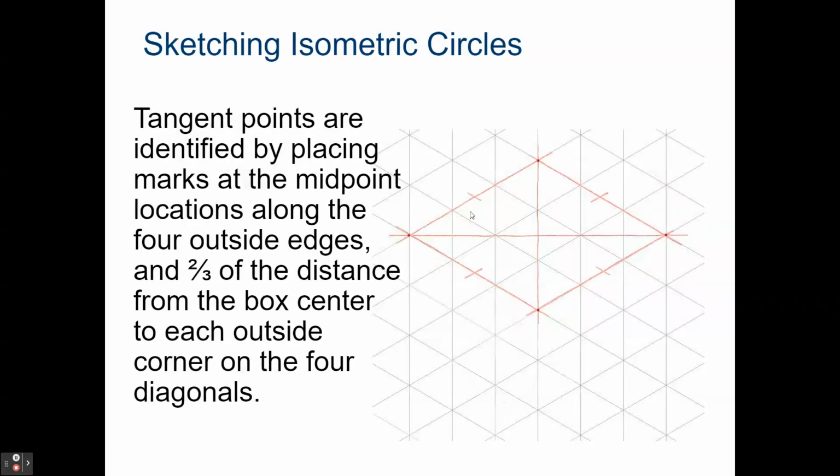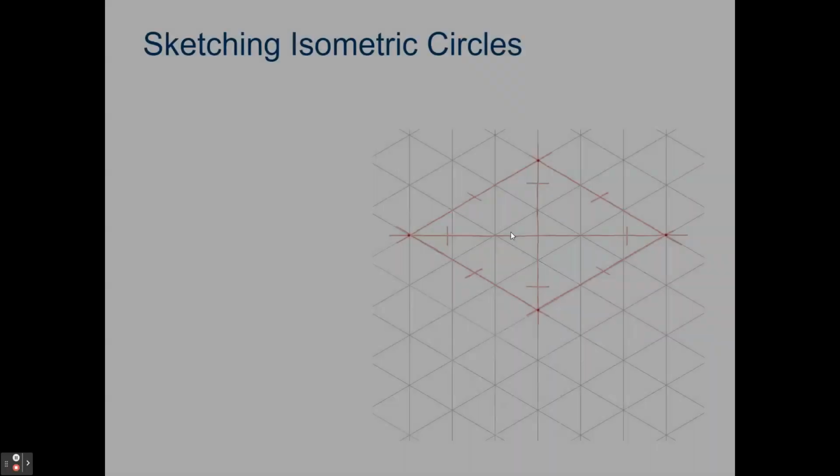And then from your center point, moving outwards, whatever your radius or your diameter is, you can start to make little hash marks on your squared out construction lines. So now I kind of have 8 contact points here. 1, 2, 3, 4, 5, 6, 7, 8. And between those 8 points of contact, I can start to draw out what my elliptical shape might look like.